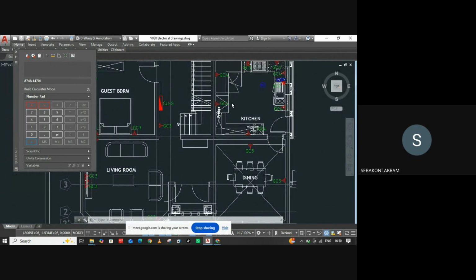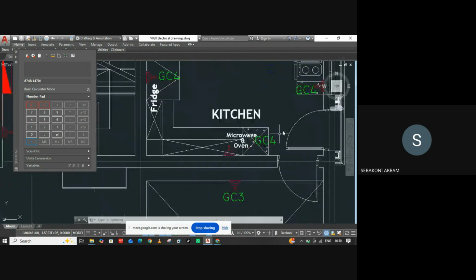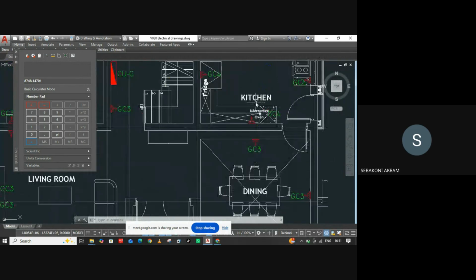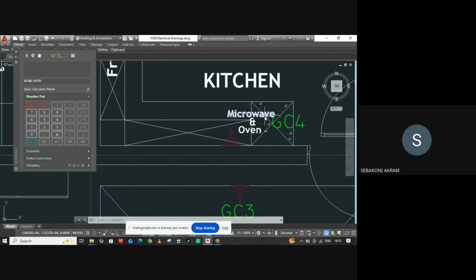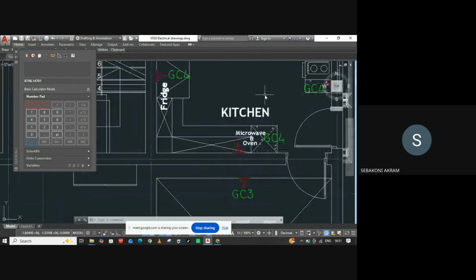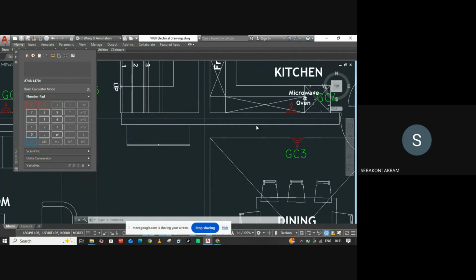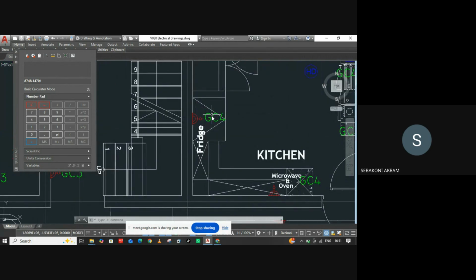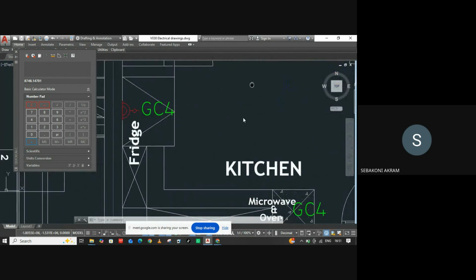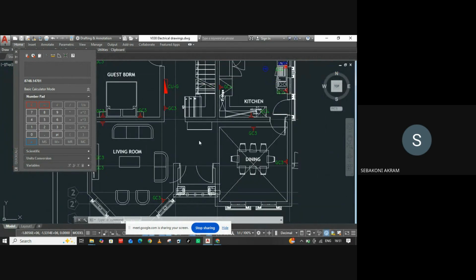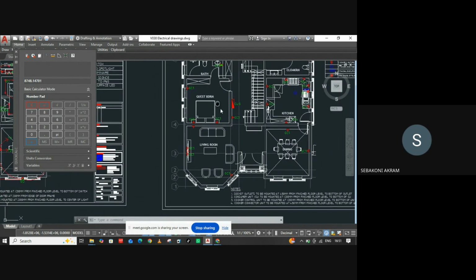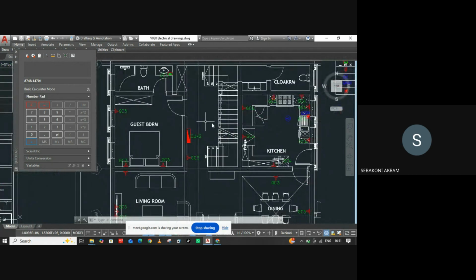So it is very good and very appropriate to separate the circuit that is supplying the kitchen appliances from the rest, because these ones are really heavy and they have different characteristics, different behavior from the appliances being used on this side. You getting me? So really the kitchen circuit is separate from this. That's why here we selected circuit 3 supplying everything else on this floor, because it is really small.